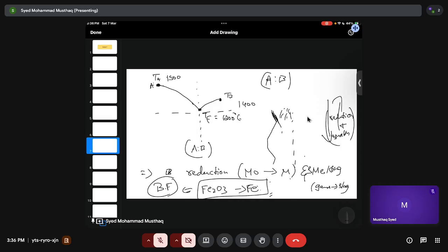Now what we do is we take lump metal oxide ore, or you make concentrates, or pellets or sinters, depending upon what you are trying to do, and they are smelted under highly reducing conditions with some reducing agents, and then you also add flux, so impurities react to form slag. The reducing agent can be carbon.